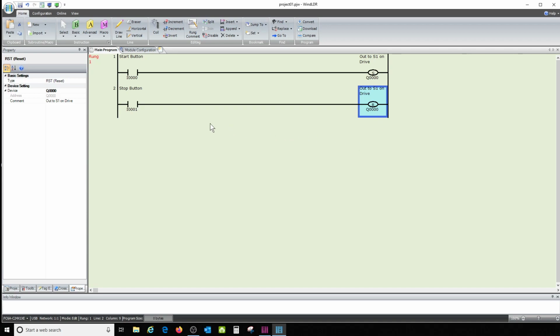That's the easiest way. And yes, by the way, physically, you're supposed to have e-stops in here. You should have an e-stop relay in between some of this so it can't run, but we're doing this basic. All that comes later. And it is true, you should really set up to where it fails to off, not fails to on. But anyway, this is the gist of it for right now. We'll dig deeper into it later.